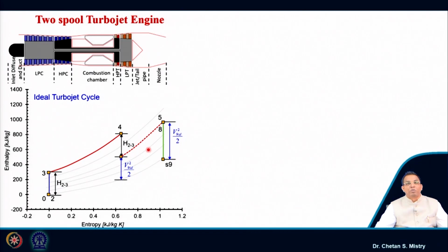Suppose we are looking for our exhaust velocity to be in this range. Under that condition, if I put in more turbine work, then my turbine entry temperature requirement will be very high, and we have realized we have a metallurgical constraint with the turbine blade material. At the same time, we have mechanical constraints in terms of centrifugal forces.